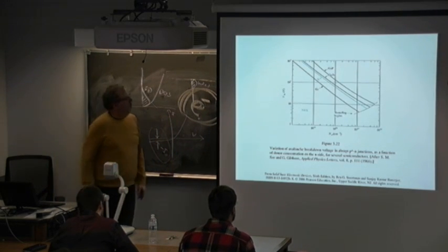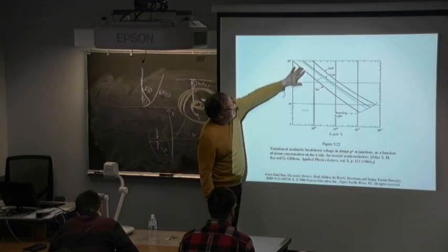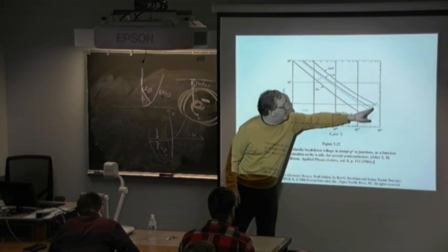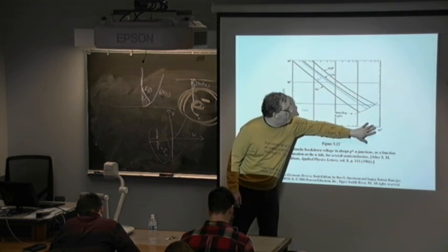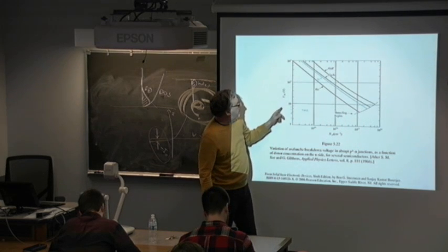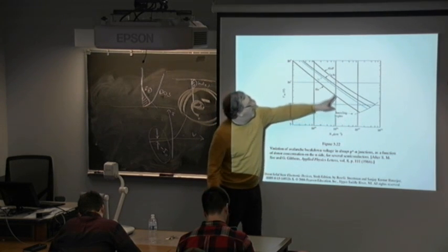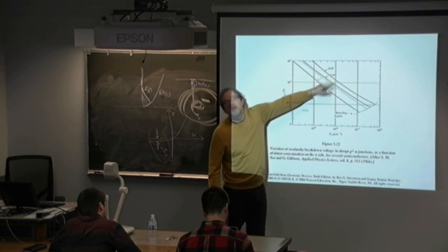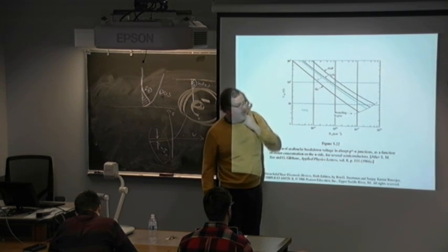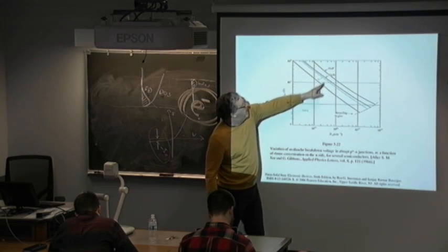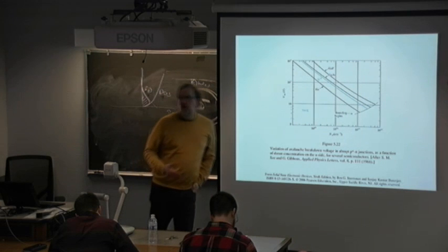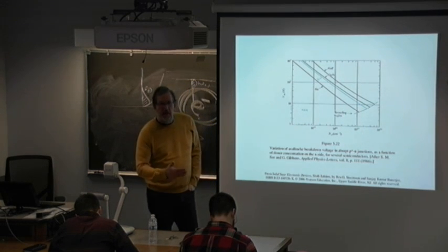Okay. So the breakdown voltage usually follows this formality: quantum mechanical tunneling happens right away at these high doping levels, or it doesn't happen at all, and then it's going to be avalanche breakdown. And avalanche breakdown is going to be band gap dependent, right? Because the higher the band gap, the higher the voltage it can sustain, and so forth. So this is why you see wide band gaps being used for power devices.